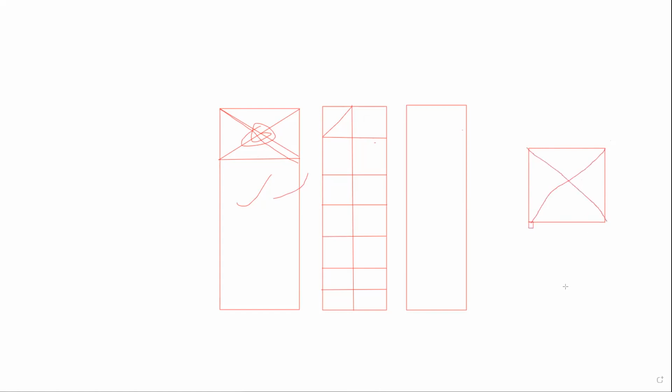So apart from this damper, we have the other one that is called Diagrid. In Diagrid, you are already seeing this structure with the bracings, cross bracings. But see, what is the difference between this moment frame and this Diagrid frame? Their outer periphery, try to understand, like see, we have this outline of the structure. So their outer periphery columns are going to be inclined to each other. It means the bracings you have provided in the simple structure, that is moment resisting frame structure, here we have to replace all the straight columns with inclined members. Got it?